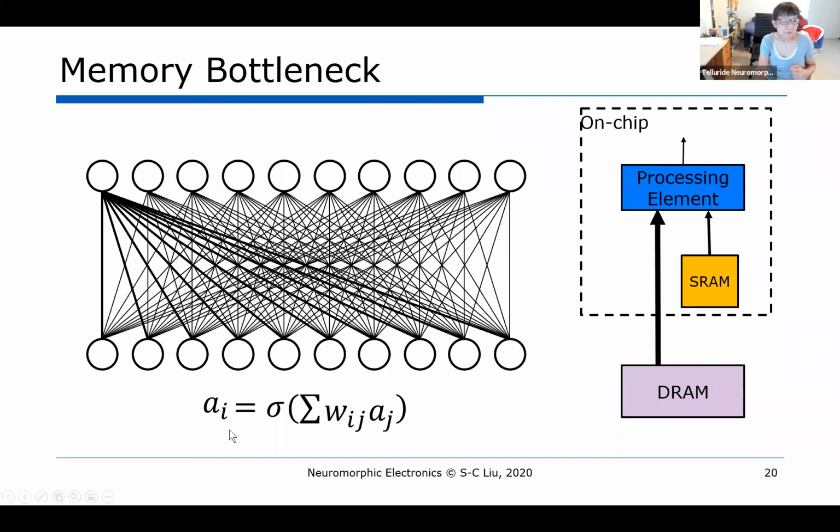This is the analog neural network where we're now going to first fetch the activations. Usually you can store these either in SRAM or DRAM. It really depends on the architecture that you're running. Then you have to fetch the weights, right? In this case, we started in DRAM, so now we have to fetch them from DRAM. Once you have the weights and the activations in the processing element, it does the summation, the sigmoid, and then you get the value for the activation of this neuron, right?